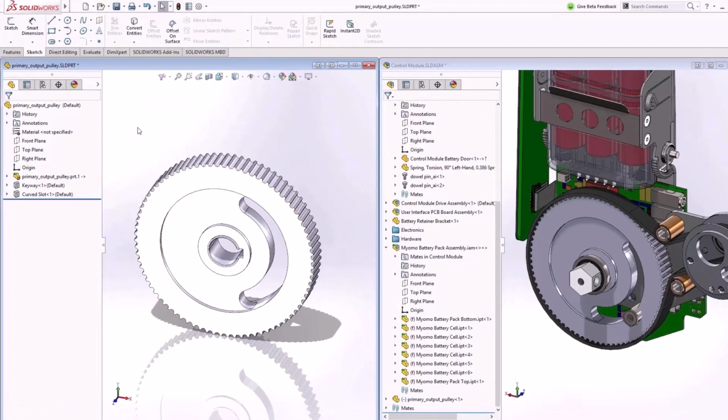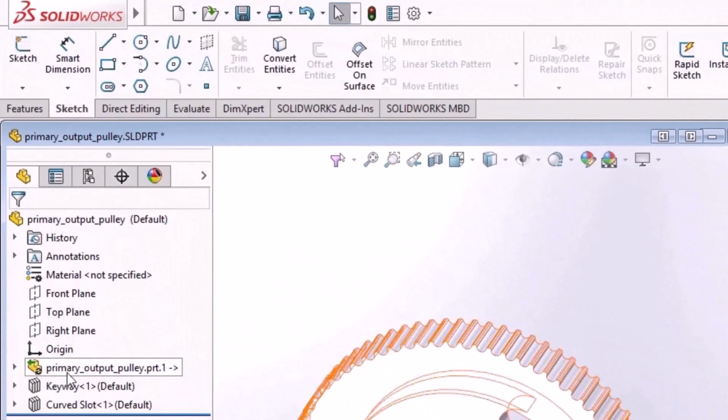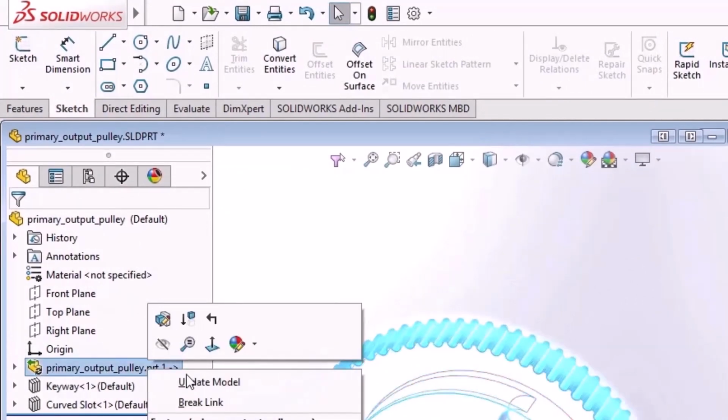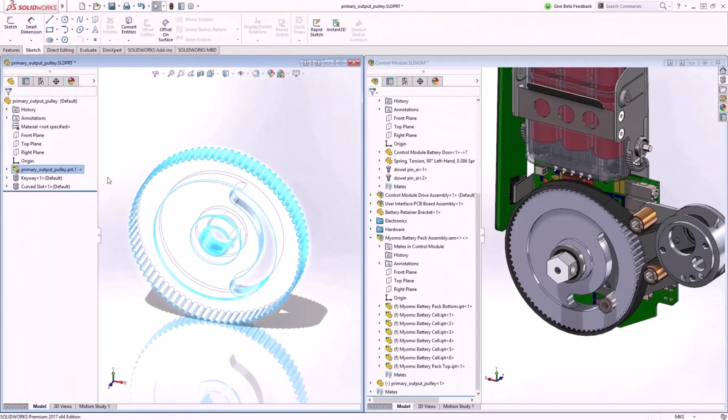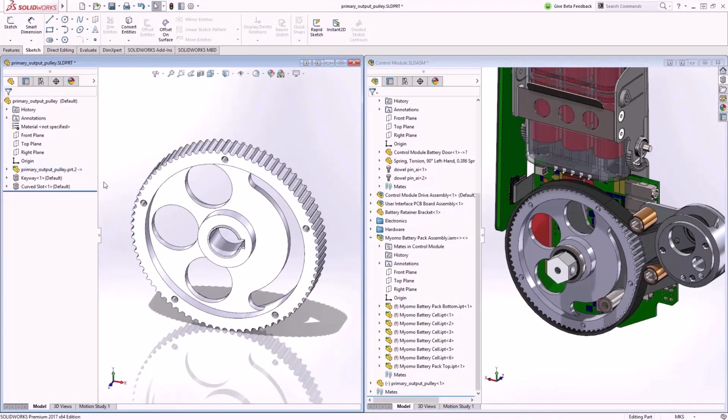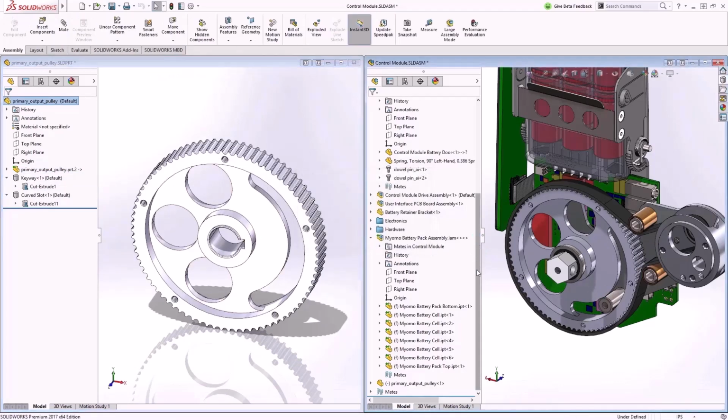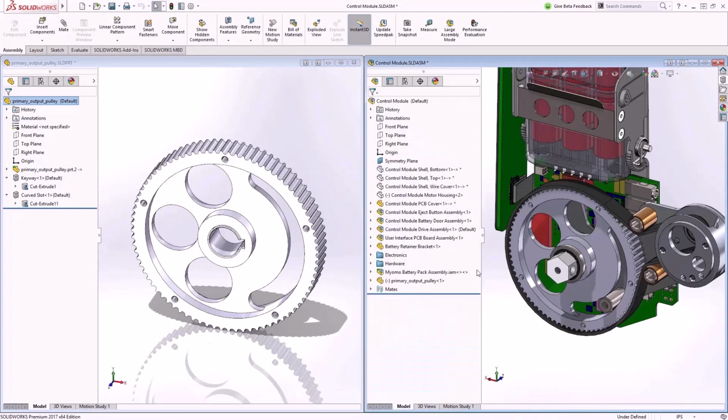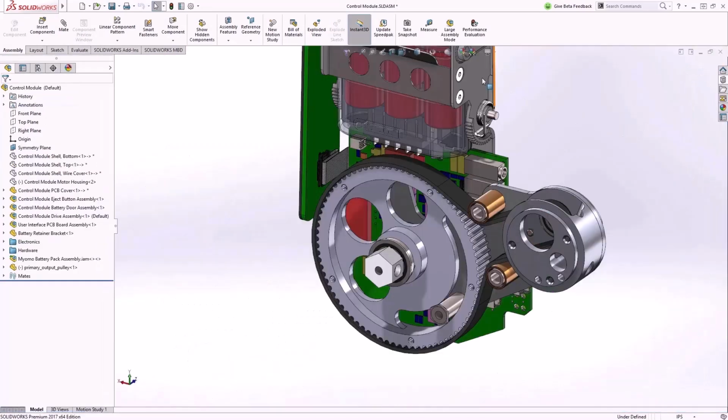And then in SolidWorks, you'll see a little refresh symbol on that part. When you see the refresh symbol, all you got to do is right-click and hit Update. And those updates from the other program flow right into SolidWorks, and the features in SolidWorks are not broken. It's the same face and edge IDs. The assembly and drawing references are not broken. All of the updates just flew right into SolidWorks through what's called 3D Interconnect.